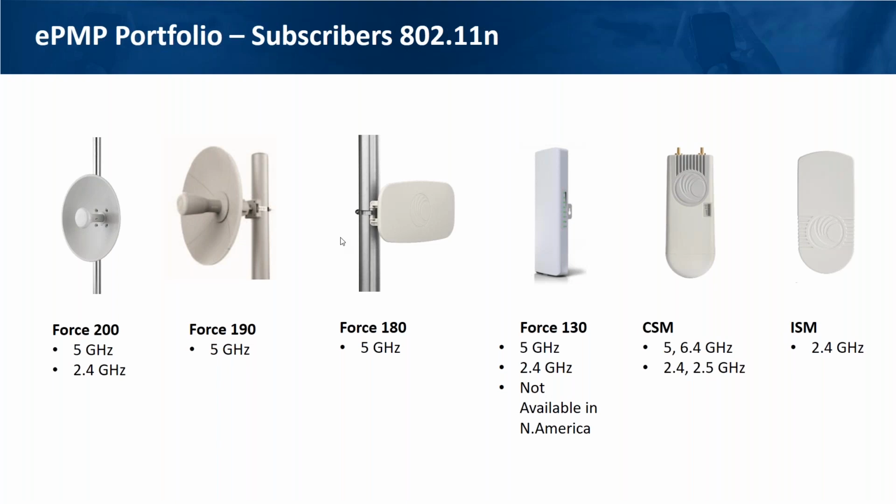There's a question about beam steering, and whether it would be recommended for somebody using an ePMP 3000 in a CCTV application. Uplink beam steering really helps with interference in the uplink direction. So you may get some benefit there, because the way the beam steering antenna works is it forms beams to the SM as it speaks to it.